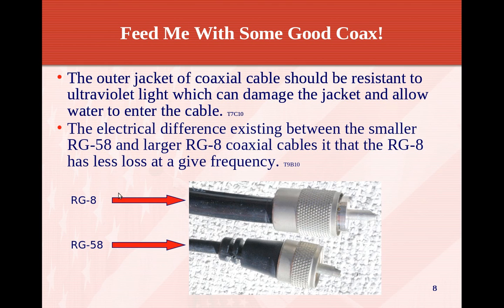And there's actually better coax out there. I like to use LMR 400 Ultraflex. It's the same size as RG8 but with less loss. And I like to use LMR 195 wherever I'm going to put an RG58 equivalent in. Again, those other two coax I just mentioned have a lot less loss at higher frequencies than these guys. And this is a PL259 end right here.